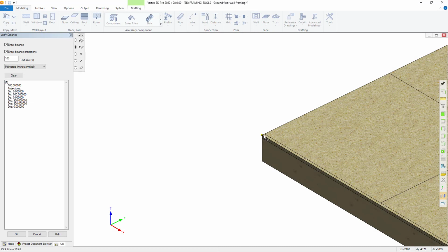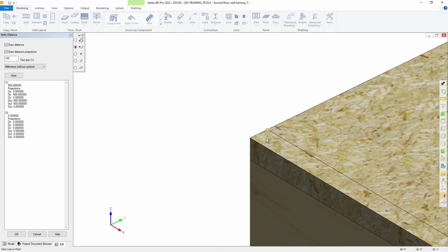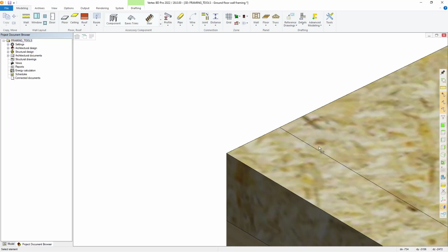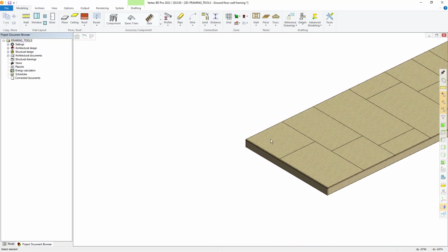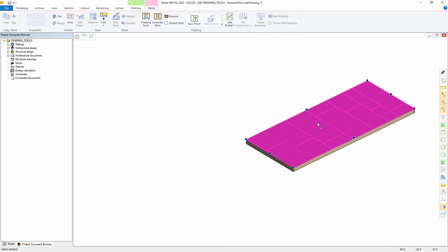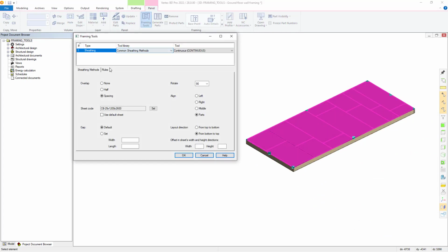On the other side of this panel, we have a small sheet, something we would like to avoid. So let's check the dimensions. As you can see, it's 22.5 mm. Now that's checked, let's edit the minimum width of the sheet setting and generate parts again. This will remove the small section of sheet from the layout.